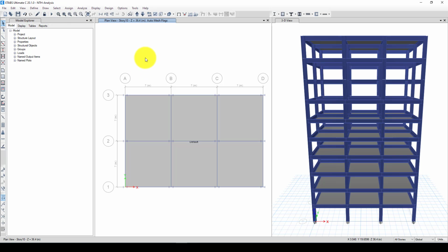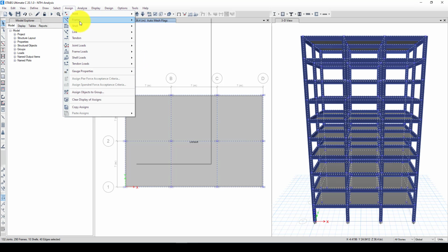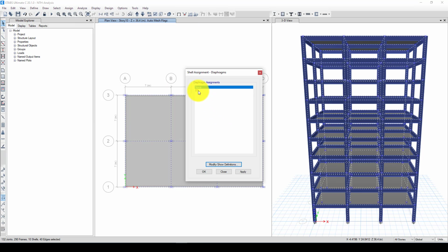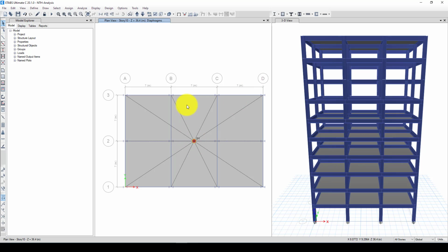But before this, one more thing I should define is shell elements. I want to define diaphragms. Okay, now a diaphragm is also added because we want to consider the displacement at the center of rigidity. So now we can run it. In comparison, you can remove the hinges and do the same without hinges and see how the structure responds, and the analysis time will also be very fast in case you do not define hinges. So now it's starting to analyze, and it takes a little time, and it starts the nonlinear time history analysis.